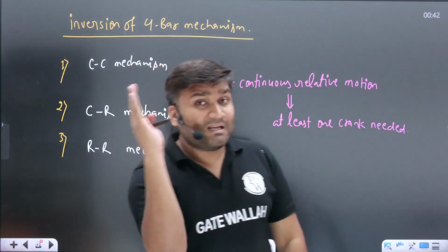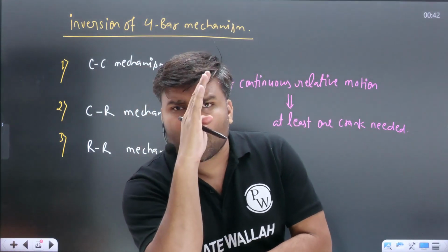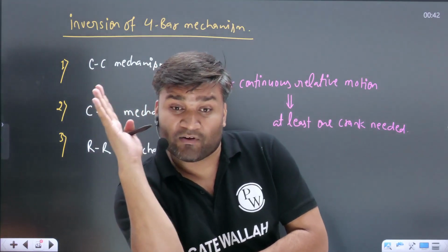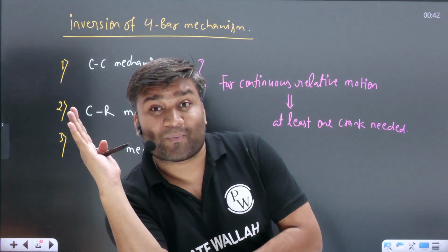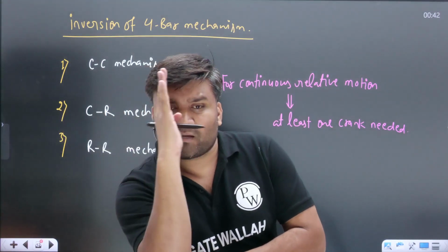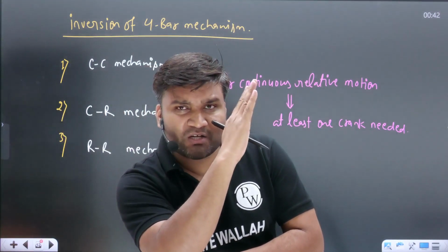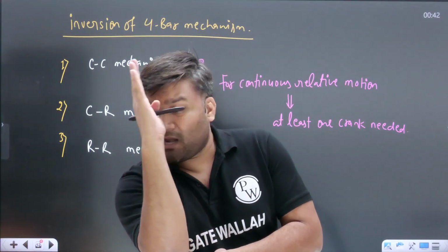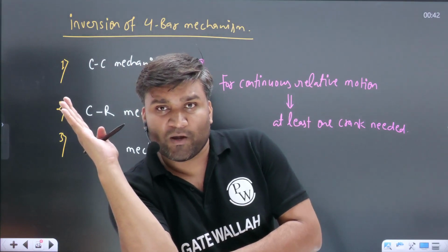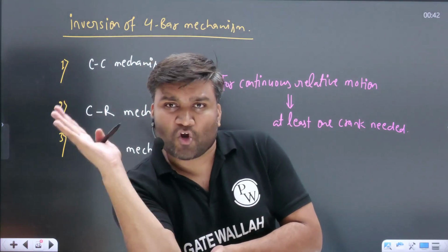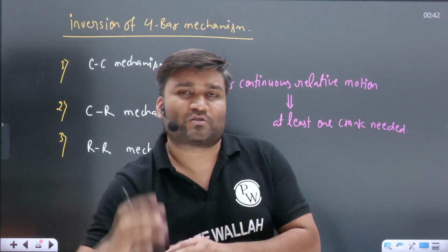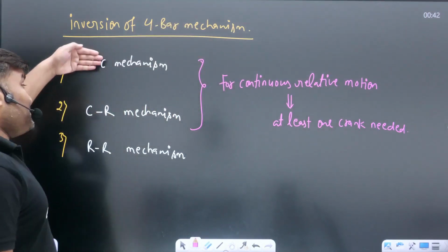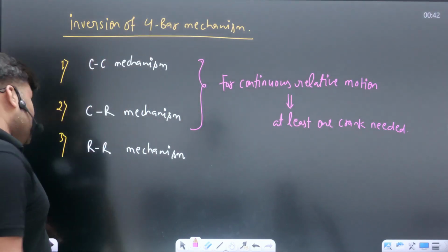क्योंकि rocker का basic behavior ऐसा है that rocker, if it is going to have motion, at some point of time it is going to stop. Again it will come back. And when it stops, it breaks the motion. Again it will come back. At some position it will again stop. Break the motion. Again it will start moving, and at extreme position it will stop. Getting a point? So rocker का motion, it will stop at extreme position. Zero velocity, again zero velocity. Crank will have continuous rotation beta.